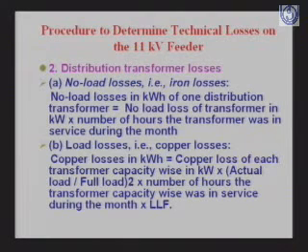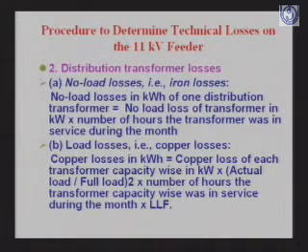So measure the kVAH recorded for a day. That gets you the average kVA. If you divide it by hours, you get the actual kVA. Now that kVA divided by the rated capacity of the transformer, the square of this ratio multiplied by full load copper loss. It's very simple, and they use this type of method.